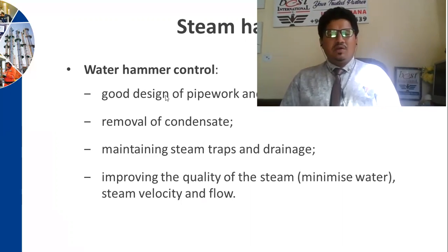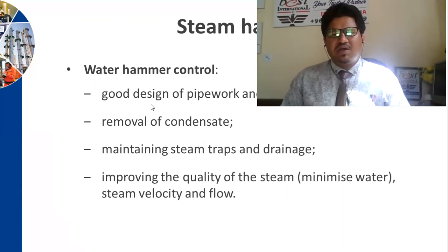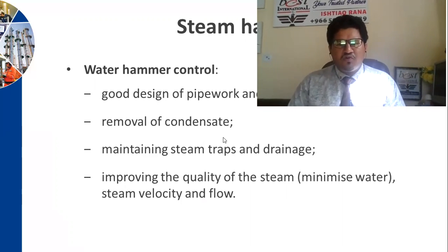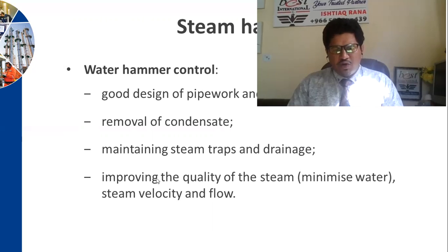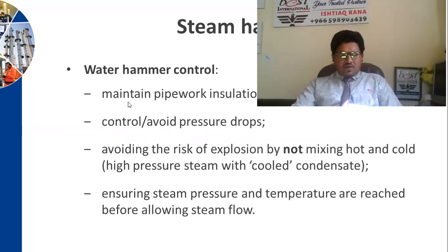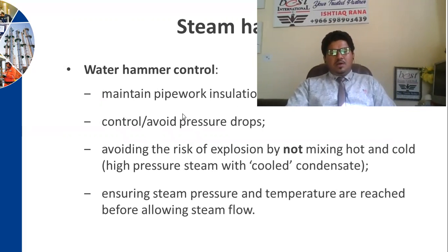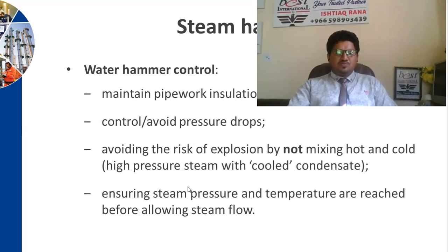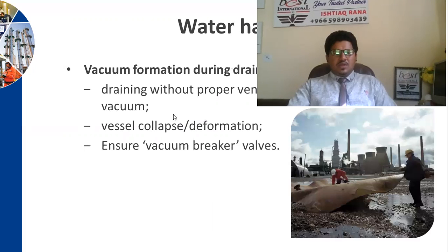So for water hammer control, make sure you have a good design of pipework. For process control, removal of condensate, maintain steam traps and drainage, improving the quality of the steam, like minimizing water, and steam velocity and flow as well. Some of the better controls: maintain pipework insulation, control and avoid pressure drops, avoid the risk of explosion, and ensure steam pressures are under control.